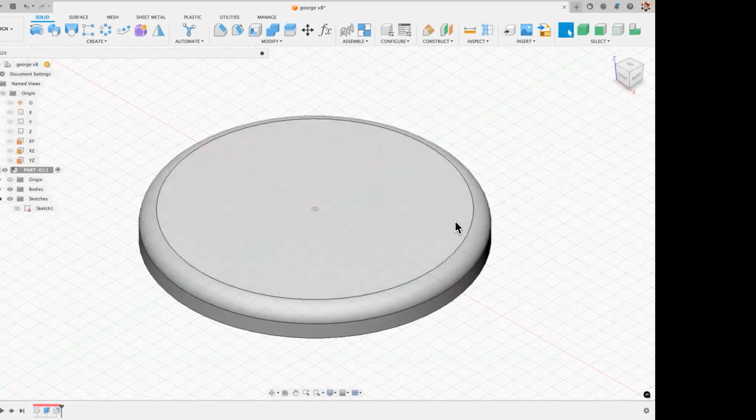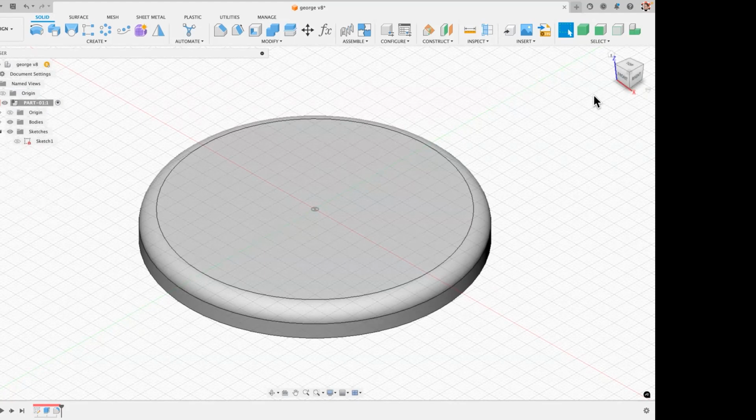Right now, you should not have any Z-axis or any indications in your viewport in the center. So nothing is selected in our tree, nothing is selected in our timeline, nothing is selected in here, and all of our origin coordinate system folders are off. Eyeball is off. Now you should be looking good. Yeah, I look just exactly like you.